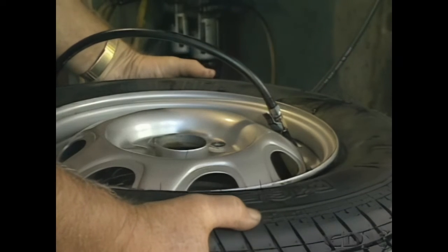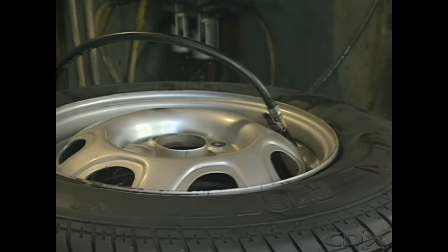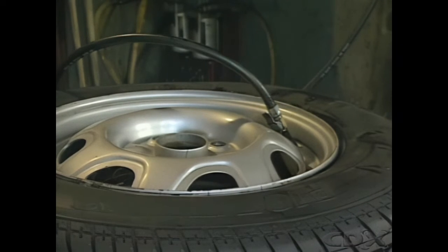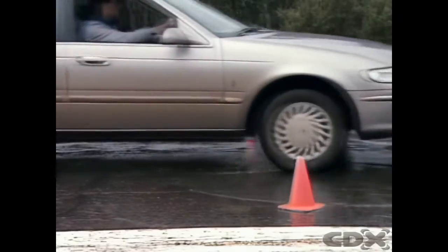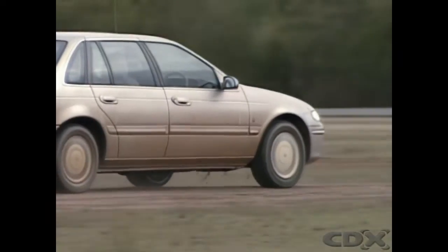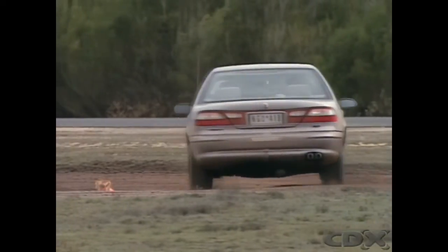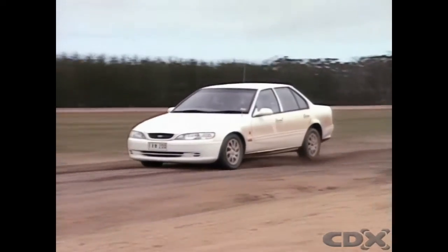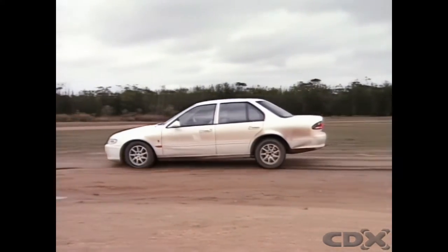The tire must be an exact fit on the rim to fulfill a number of functions. It ensures that the narrow contact area between the beads of the tire and the rim will seal the air in a tubeless tire. It transfers all the forces between the tire and the wheel without slipping or chafing. It ensures the friction between the tyre and the rim prevents the tyre turning on the rim.